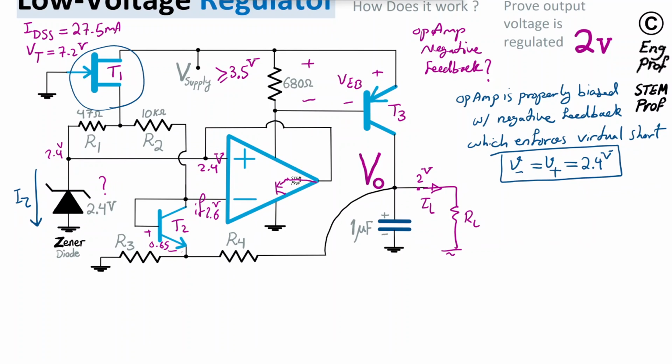So let's see what's happening with respect to the transistor T1. We have the gate voltage equal to 0 because it's grounded. We have the source defined by the Zener diode current. So we have IZ. We can make the assumption that this IZ is the dominant one. So we are going to assume that let's say the IZ is mostly passing through the 40 ohm resistor. If not, that's fine.